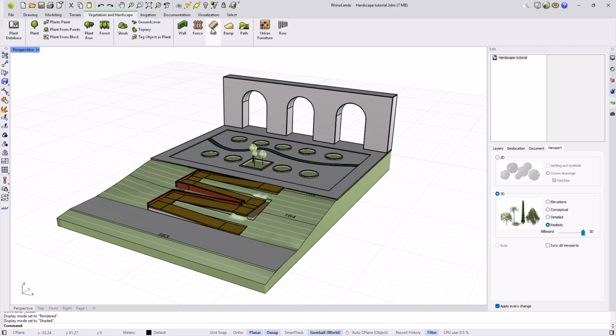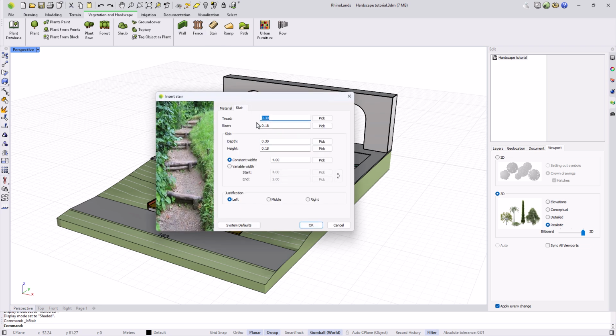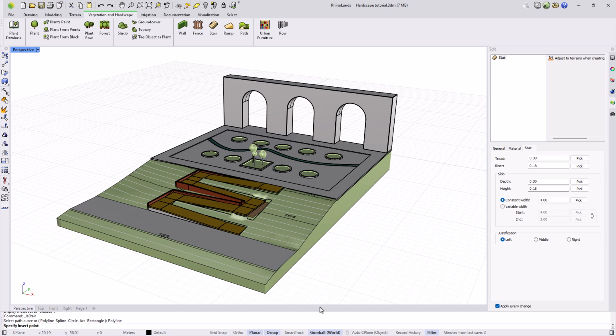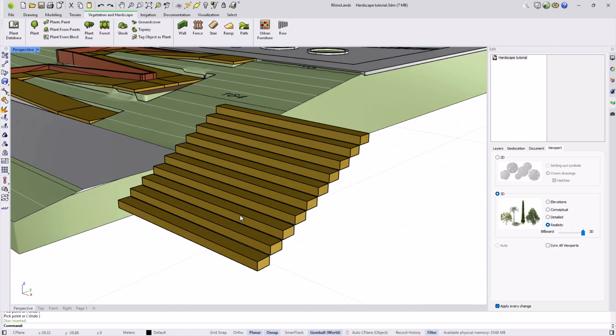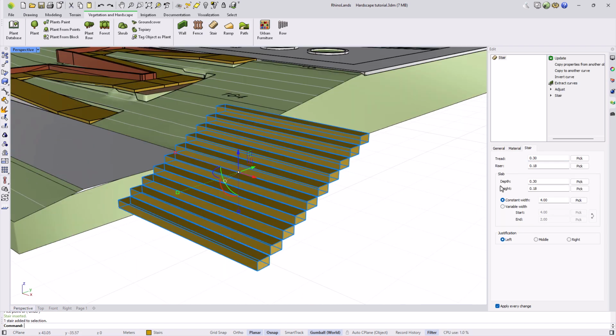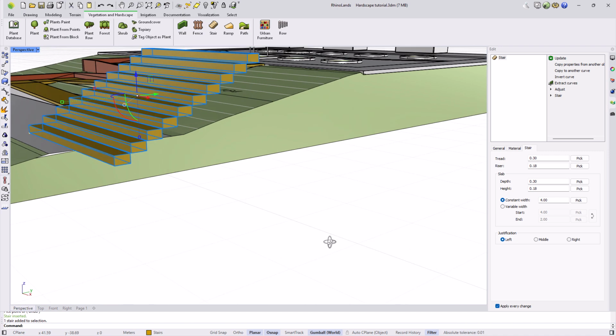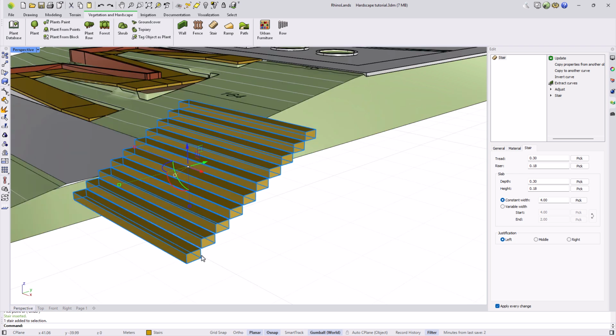For the stairs, we configure their parameters in the same way. We accept and select a line in the drawing or create it. In its parameters to configure, on one hand, we have the dimensions of the slab and, independently, the total of the tread. If we match the two values, each step will be perfectly aligned.